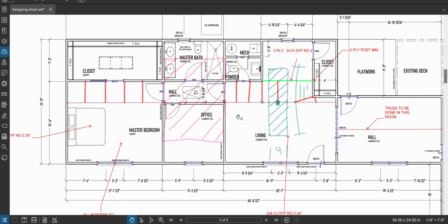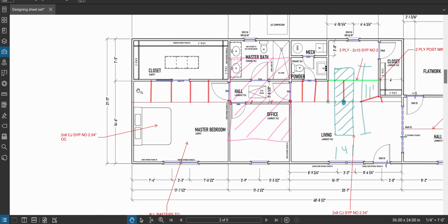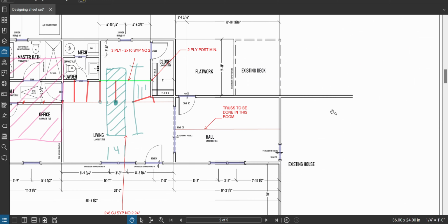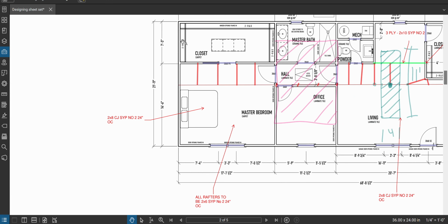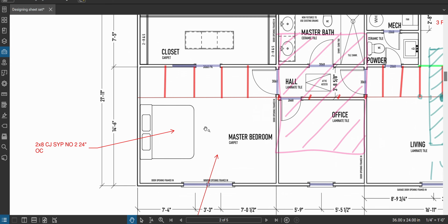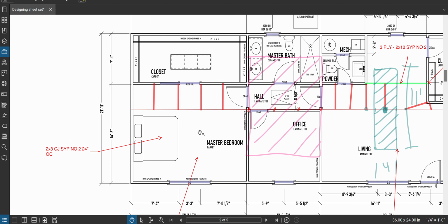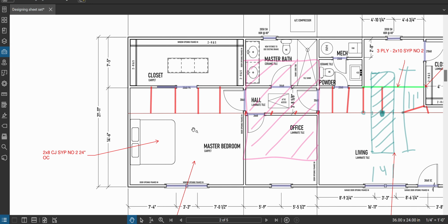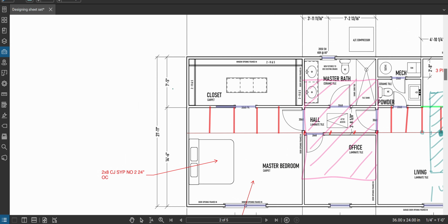Gable bracing. Okay, so the left side of this house has an exposed gable. The right side of the house is tied in somewhere else, so I'm not concerned with that. So on this side, I have this gable wall here. What I need to do is make sure that this gable wall isn't going to buckle under a wind event, which is technically in the wind category, but sometimes ends up in the gravity category. But the basic premise is this wall.